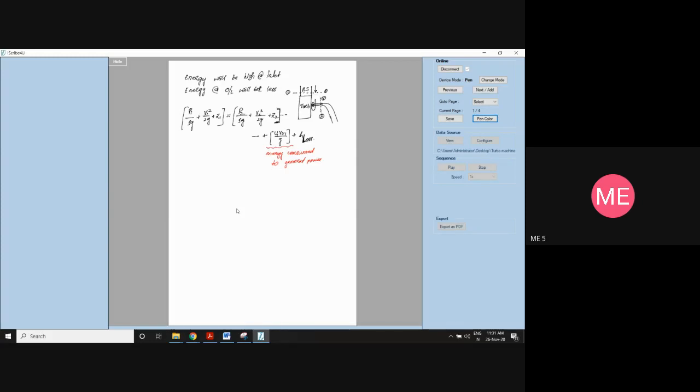Next. So he is asking head loss, right? So we'll find out head loss between the inlet and outlet of the runner. HL is equal to P1 by rho g plus V1 square by 2g plus Z1, minus U1 Vu1 by g, minus P2 by rho g plus V2 square by 2g plus Z2. This is the final equation where he is asking you to find out the HL.